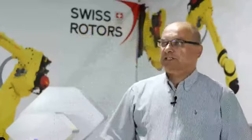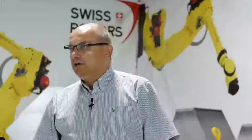There were losses on the drive, the pulleys and belt, of course. Now everybody is switching to higher efficiency. They would like to have a high efficiency drive, so the losses will be much lower than in the previous design. And instead of normal AC motors, everybody is starting to use EC motors, which have much higher efficiency.